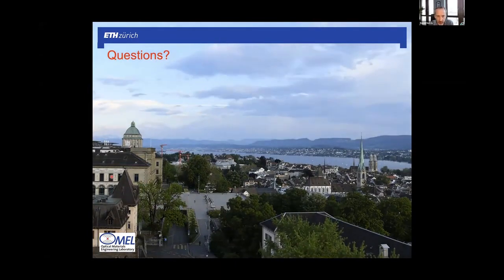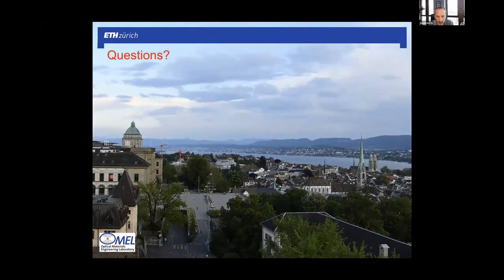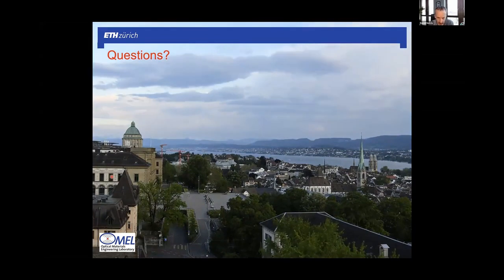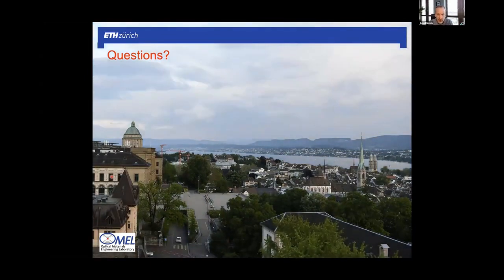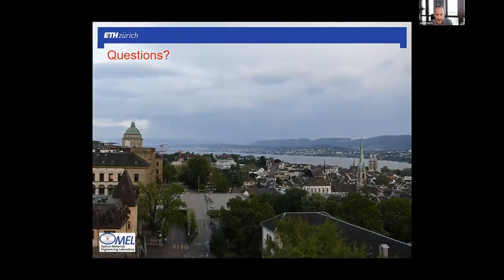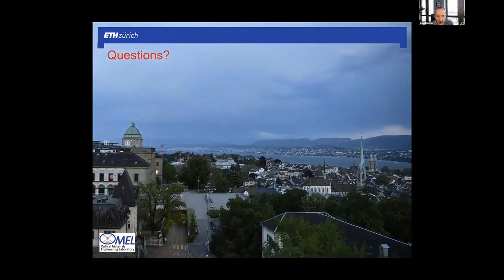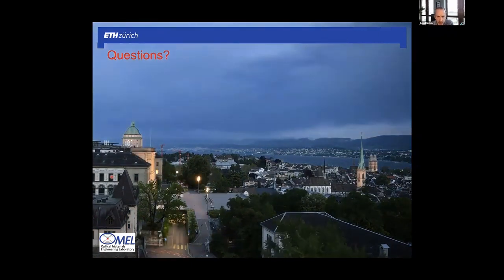The gold can be very thin. I mean, gold is much more forgiving in the deposition than silver. So you can make 10, 20 nanometer thick layers of gold that are very flat and then can be used in this way. And for gold structures, you could get away with making it thin and even semi-transparent if you wanted that for some reason.